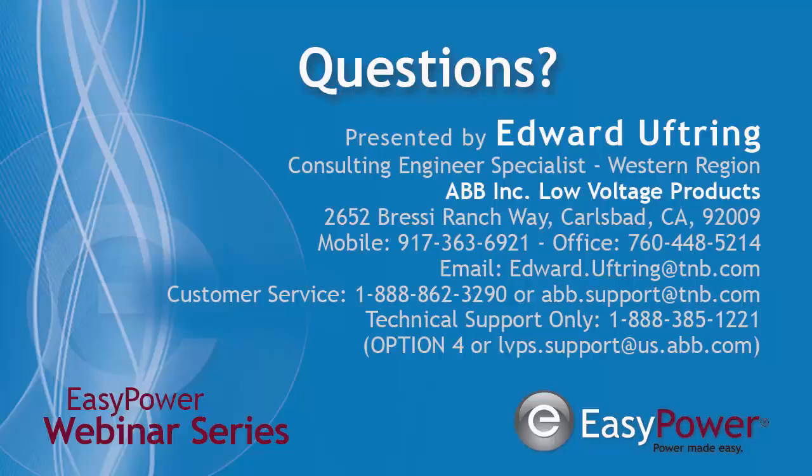Does the breaker short circuit condition include phase to ground shorts in addition to phase to phase? We actually have a separate protection for that. It's called the ground protection. So you will hear LSIG. The G is phase to ground. You can get that on not all of our breakers, but the Emax breakers will come with that identification so that you can, yes, have a fault that will look at phase to ground shorts.